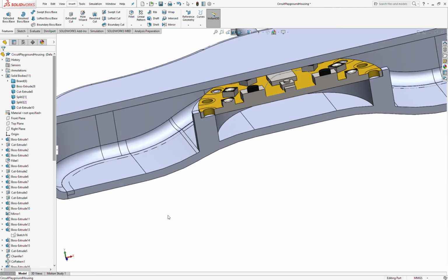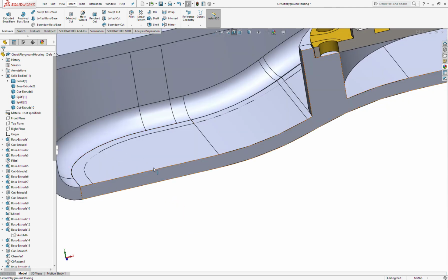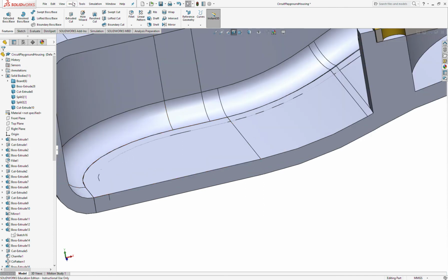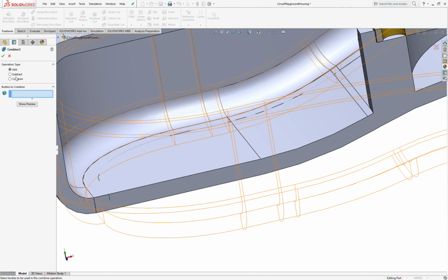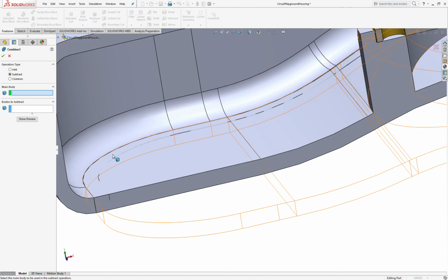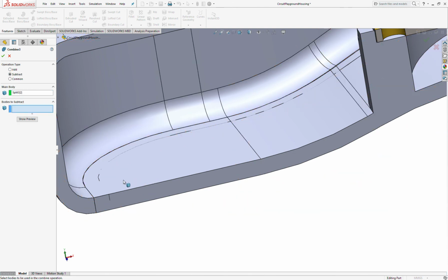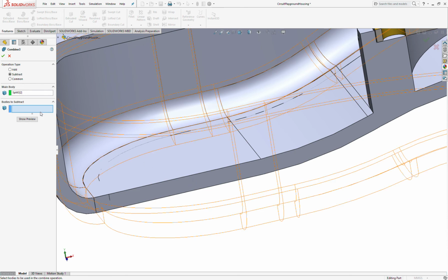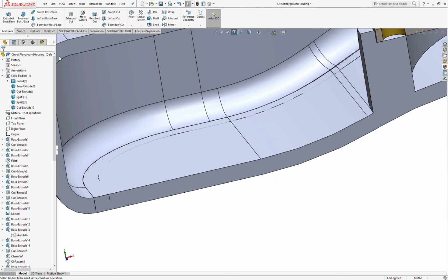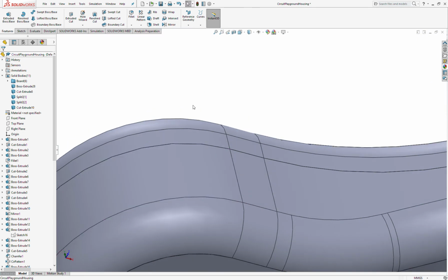So now what we want to do is basically remove this lip from this part. And then add it to that. Which we can do with insert features. And we're going to go to combine again. In this case, we want to subtract. Our main body is this one, and our body just, whoops, it doesn't like it that I'm in the section cut is what's going on.